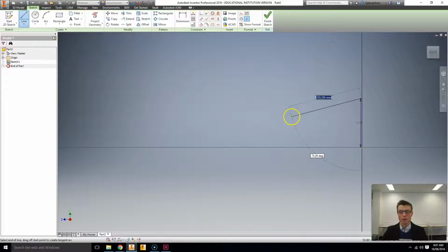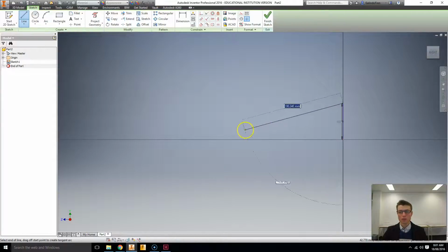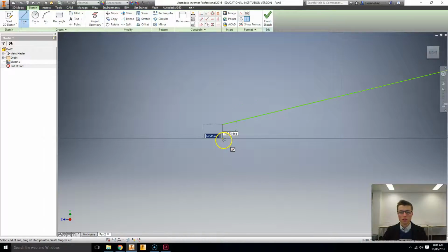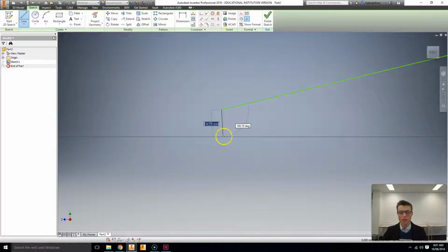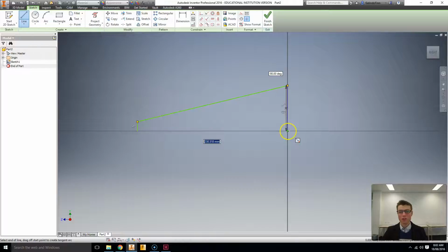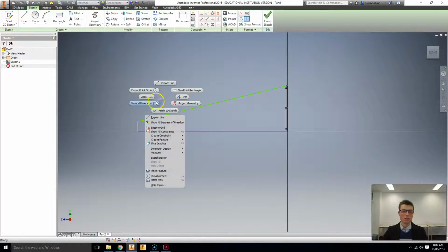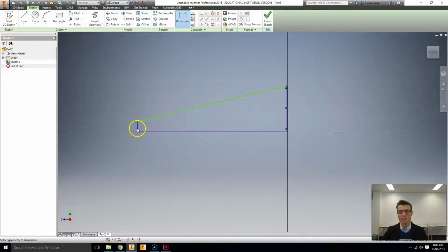Then I'm going to very roughly, zooming out with the mouse wheel here, just select down in the distance here, making sure I'm selecting a vertical straight down line. It kind of snaps to that vertical, and the end point of my line is on the horizontal line here. They both kind of snap, and then I'm going to close off this shape, which, if you have started your dragsters, looks familiarly like a billet shape.